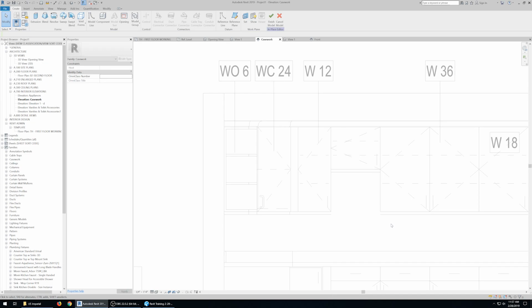But here's the point of modeling. Right now, do you know where you're modeling in 3D space? You don't. You need to define that. And that's where you have to set your reference plane. And when you set it, it's going to ask you, do you want to pick a plane? Okay, let's try pick a plane. Let's see if we can pick this wall. All right, let's pick that wall.